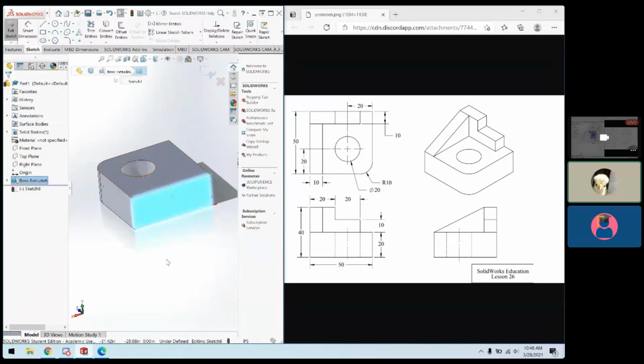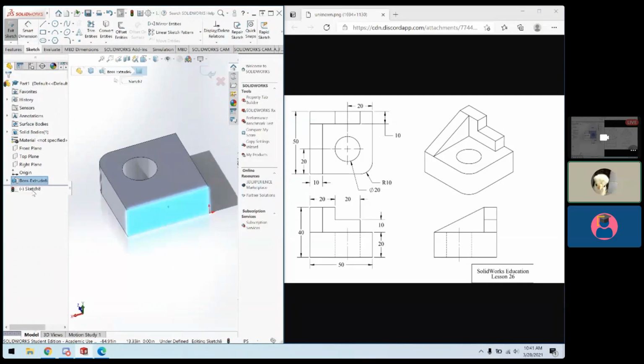So now what SolidWorks basically does is it creates a plane that is on top of this, parallel with zero distance, and you can sketch anywhere on this plane that is coplanar to this, and you can extrude it or do any features you want: extrude, revolve, the options are there. So now I want to be in the normal view of this sketch plane, so I would right